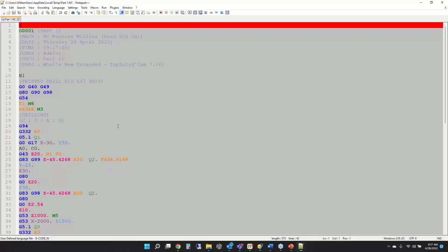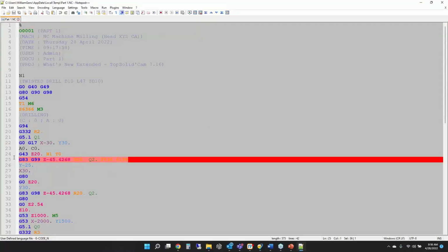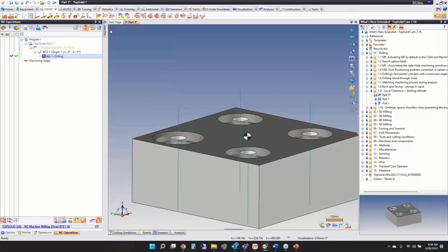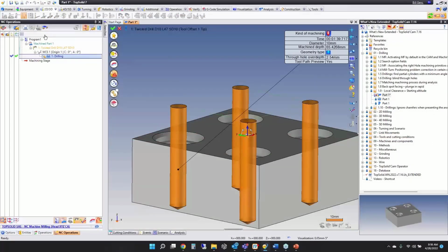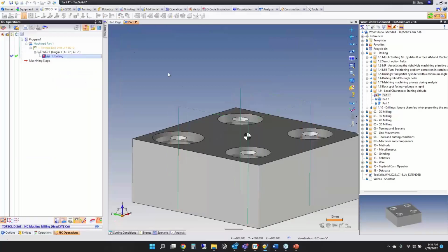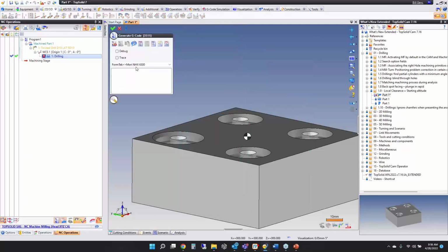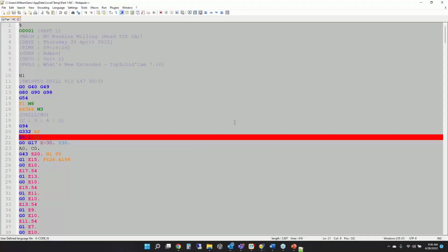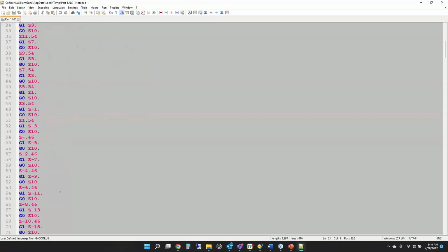you can see cycle. Now, if you go and override the altitudes, this is the default setting now here, and I go to a value, and I say 10, for example, and then I go generate my G-code. Now you're back to longhand code.